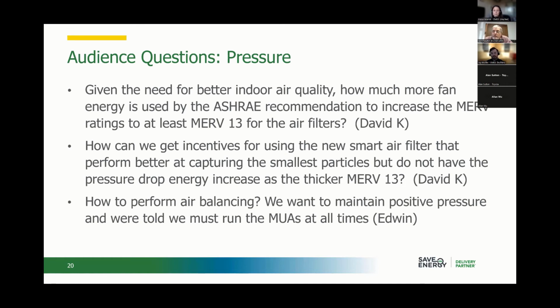Quite often they'll be putting in what the pressures are at these different points. Whether or not they're actually doing a delta P across the fan, though, is another question. Whether or not they're able to locate those points on a fan curve and measure the power at the same time, which would seem like such a small jump, in order to make sure that once you've got the air balance report, you also know what your fan efficiency is.